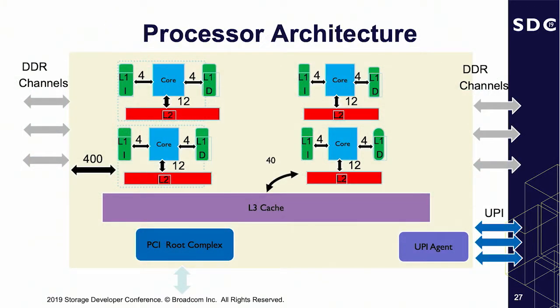I'll go into one processor. Basically, this is again a top-level picture. You have a separate L1I and L1D. Then there is L2. These are the caches. There is one unit, and there is L3 and root complex and all those things. I want to focus on the one core. I think since Nehalem, the L1I was 32 KB and L1D was 32, and L2 was 256K. L3 was 8 megabytes and above.